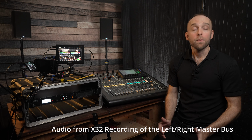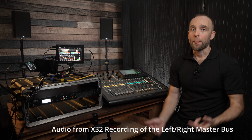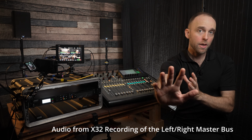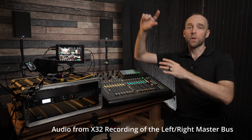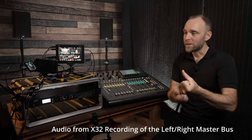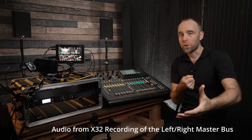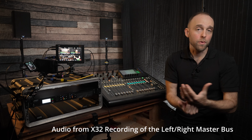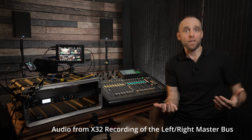So that's it. I can't emphasize enough how much you need to start at the sound source, gain up at every point along the way, pushing your signal through the system. If you start at the end and try to pull, the pulling is actually the device's own input gain or input attenuator trying to pull that signal. And if that signal is too low, it's got to pull harder. It's going to pull the noise with it. I don't know, I think that's a good analogy.